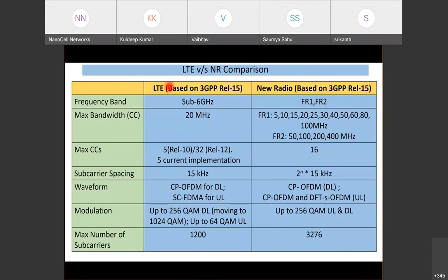Carrier aggregation, almost by necessity, because 20 megahertz. In the case of 5G NR, yes, carrier aggregation is allowed, but I think we will embark less on carrier aggregation compared to 4G. Flexible subcarrier spacing, remember, is the cornerstone, the most granular element for handling all those services, bands, bandwidth, etc. Very similar waveform, OFDM with cyclic prefix. For those of you who like nuance, SC-FDMA was a little bit of a drag in LTE. That's also coming back to OFDMA based with an option for the SC-FDMA.